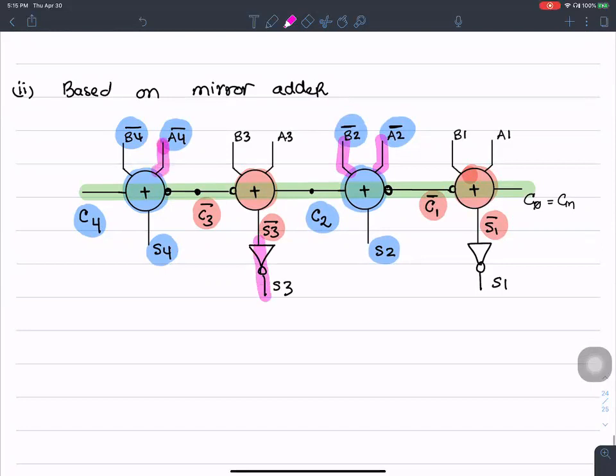So what you're doing is reducing the delay along the critical path and passing the delay on to the off-critical paths. That is fine as long as I reduce the delay along the critical path. I can tolerate a bit more delay off of the critical path. Okay, so that's what we are doing here.